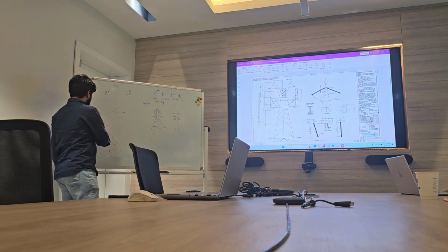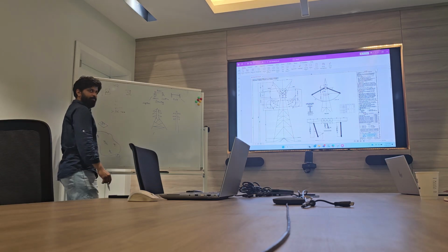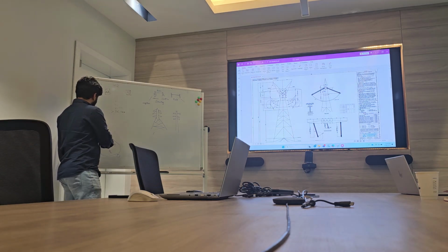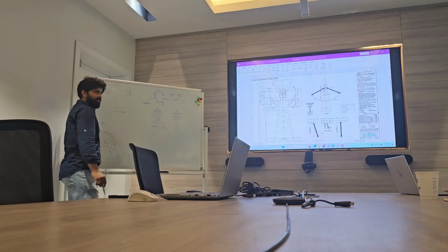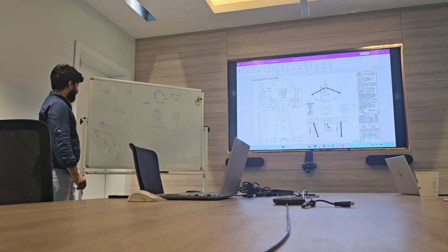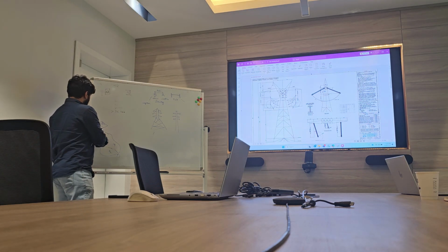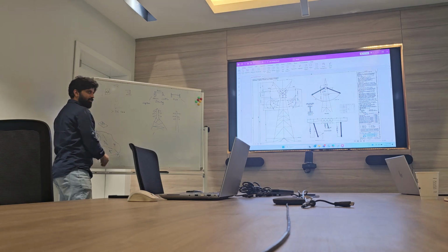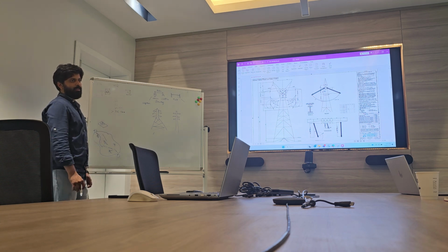But you have one substation here and another substation there. You need to connect between them. I need to find a way how to cross and reach my point. I can draw a straight line, which is fastest. But you also have to look at roads nearby, and how to access. If it is a completely straight line in the desert, how will I do it? There are many factors for selecting a route.